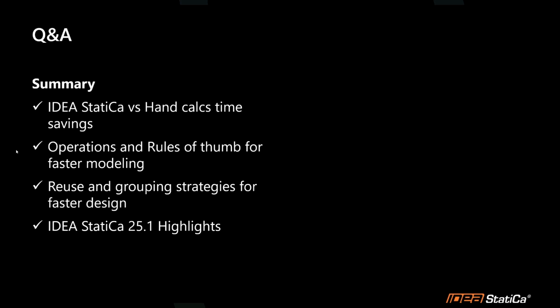These will be the component checks. And for plates, we do work with stress analysis. So the plates will be per the FEA, and then the plates are by the component checks, which is basically our method, the CBFEM, component-based finite element method. Perfect. That's right. We kind of do a mix of both. It really gives us the best flexibility to design all connections there.